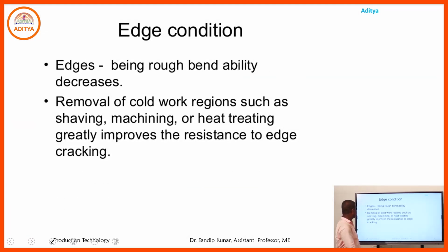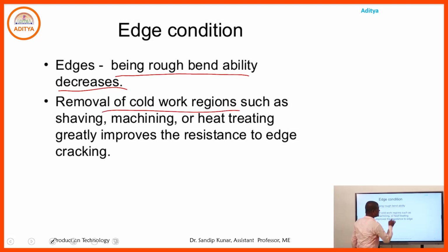Age condition: with aging, bendability decreases. Removal of cold-worked regions by shaving, machining and heat treating greatly improves the resistance to edge cracking.